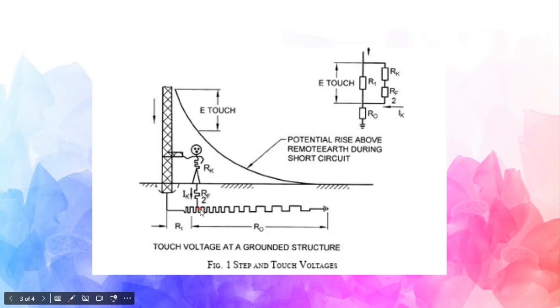As an electrical engineer, first thing, whenever you are going to a site or any substation, particularly an HV substation, always wear safety shoes. That is mandatory. And never ever touch anything, whether it is live or not live, with your bare hand. If it is 220 volt or 415 volt, you can touch it using a tester. Or if it is a higher voltage, then of course you must wear safety gloves.